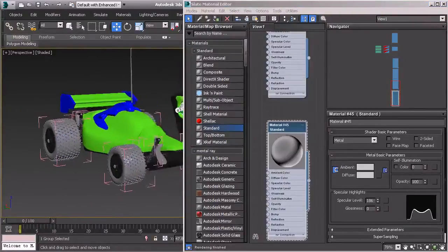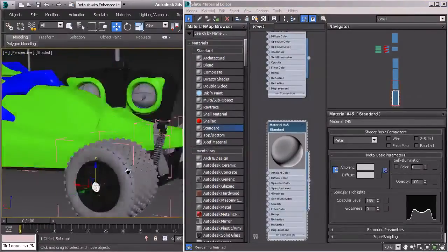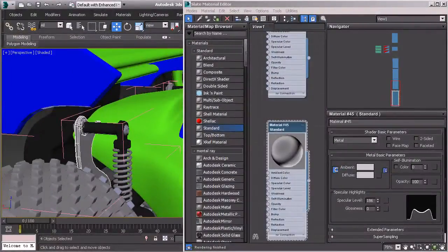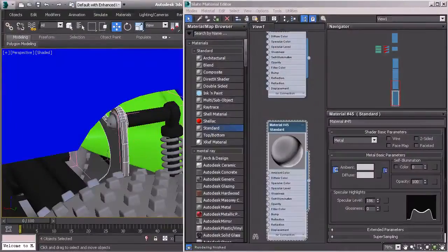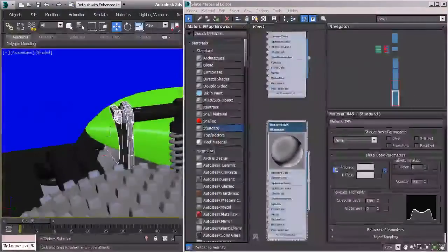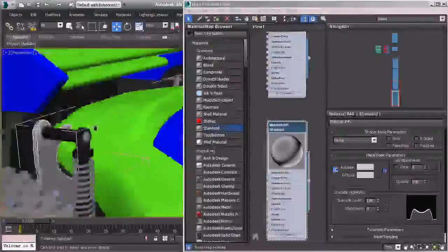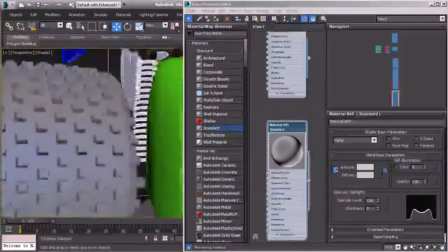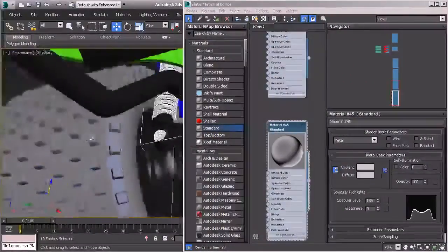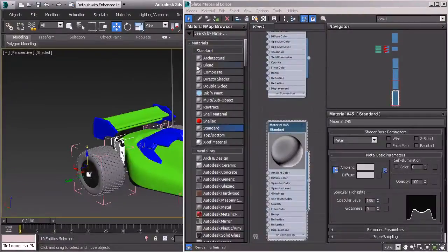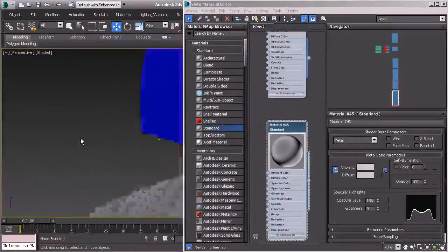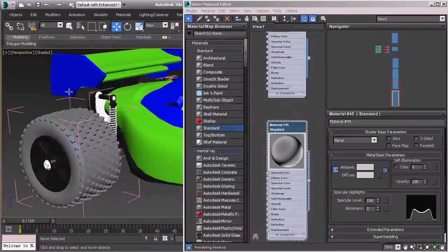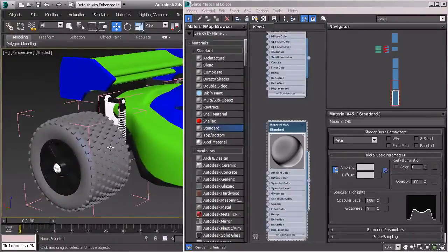So with something like this, I could select all of my objects that are supposed to have that metal material. In this case, it's going to be my connector and all my screws and washers. And you can apply those to this. I'm going to go ahead and just select one set here, and then you can go through and put those materials on there if you like, and we'll assign that. And there we go. So now we have that material, and it looks a little off in here. Whenever it renders, it's going to look a little different, so just be careful of that.